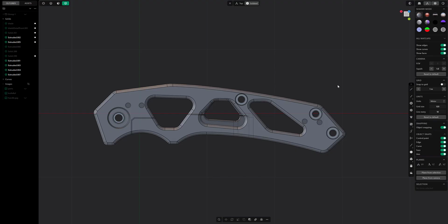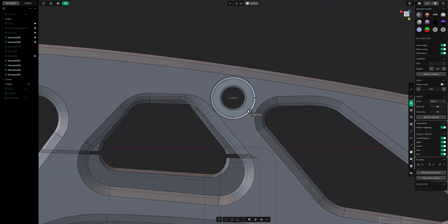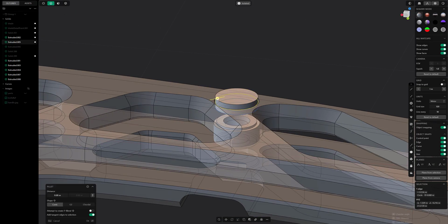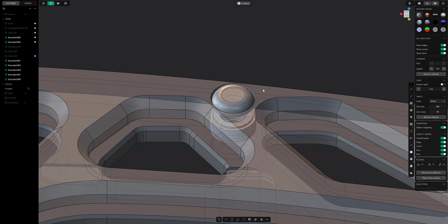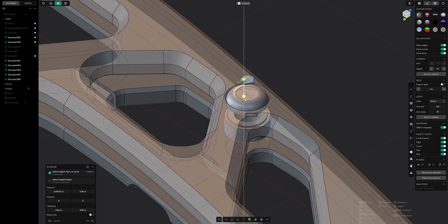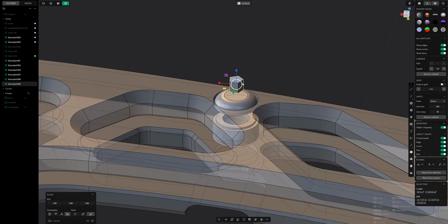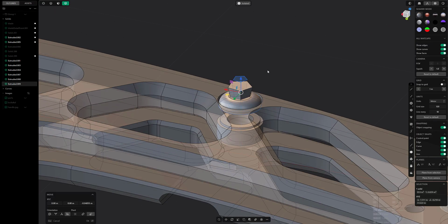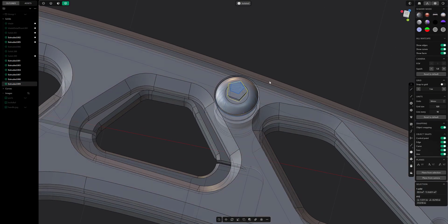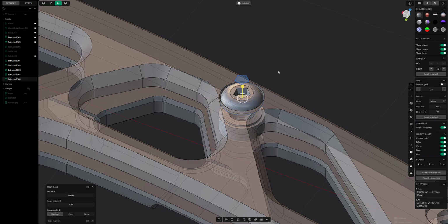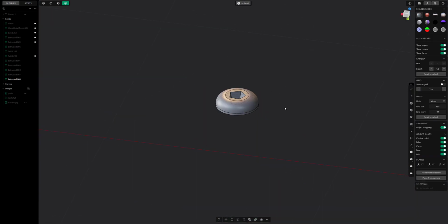We're almost there, right? So what do we have left to do? We need to make a few screws. You only really need to make one. Start with the cylinder, a circle, move it up. Go ahead and round off the top of the screw head. Polygon to create a Phillips head. Drag it down. I tend to taper these things a little bit. It tends to look a little bit nicer in the model. And so we'll punch that in with a boolean and give it a little bit more depth, right? Let's isolate the screw head, and again, let's make the screw.